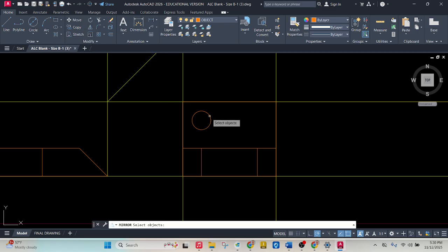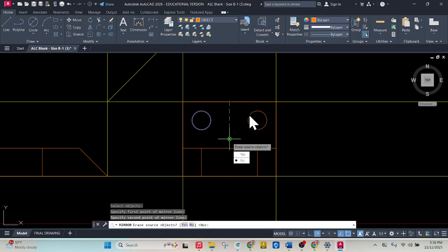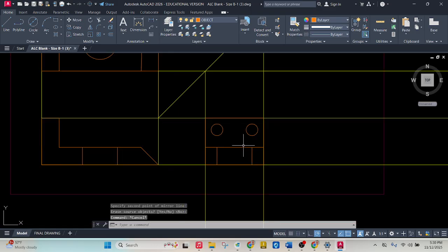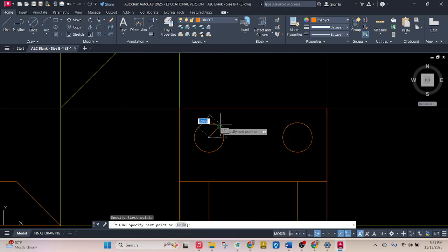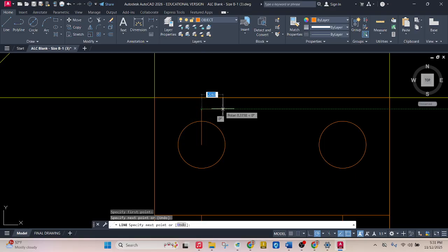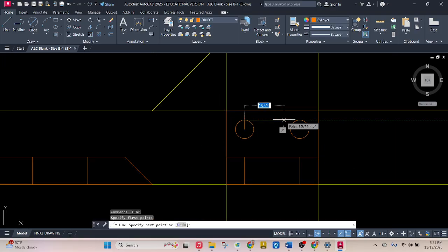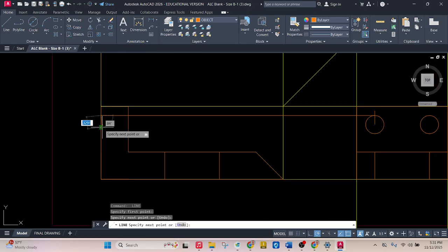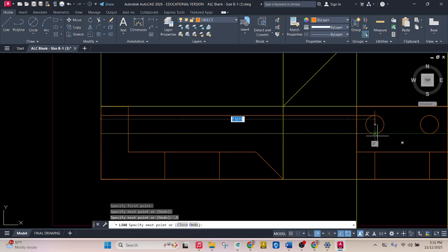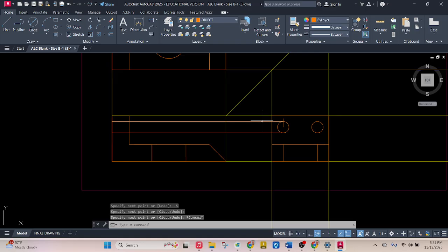Use the mirror tool. Click on the circle. Right click. That. Cool. And you don't really have to use the mirror tool on that. I think it's just a little faster and easier. Okay, and the next one, so I'm going to draw a line that goes straight up right here and make the line go over this way. Oh, sorry, the opposite way. That. And then I can go down 0.5, hit enter, and then go all the way back. You can see that this will ultimately be tangent right there. So those are good. Those are good lines we want to keep.